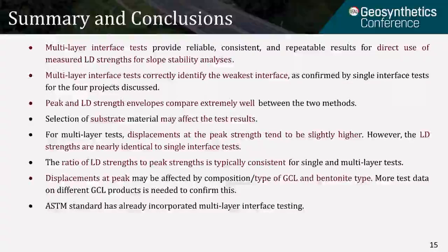Selection of substrate material appears to slightly affect the test results. For multi-layer tests, displacements at peak tend to be slightly higher. However, the large displacement strengths are nearly identical to single interface tests. The ratio of large displacement strengths to peak strengths is typically consistent for single and multi-layer tests.